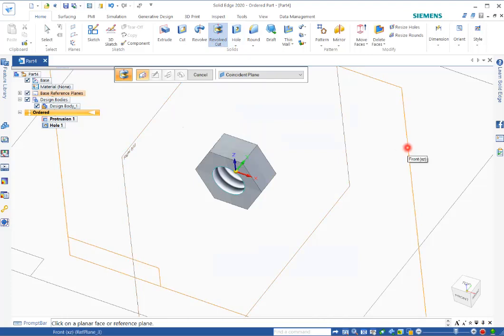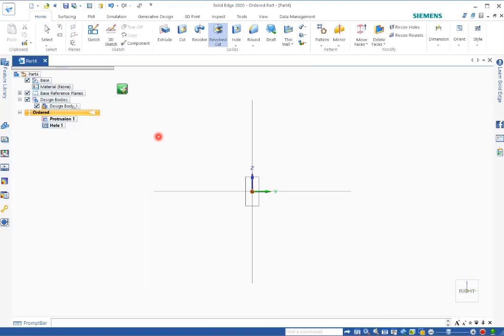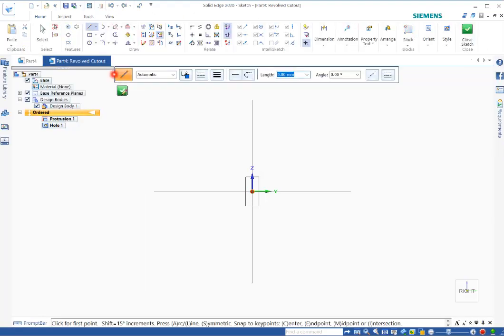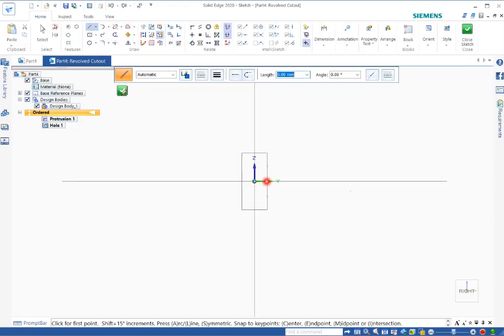Like this one is parallel with the nut. That one points to the corner of the nut, but you need this one. Click. Right. Now you can use the line command to add a line right from the corner point, endpoint pairs, and drag within the side of this axis. Click. The length doesn't really matter. I right click, cancel the command.